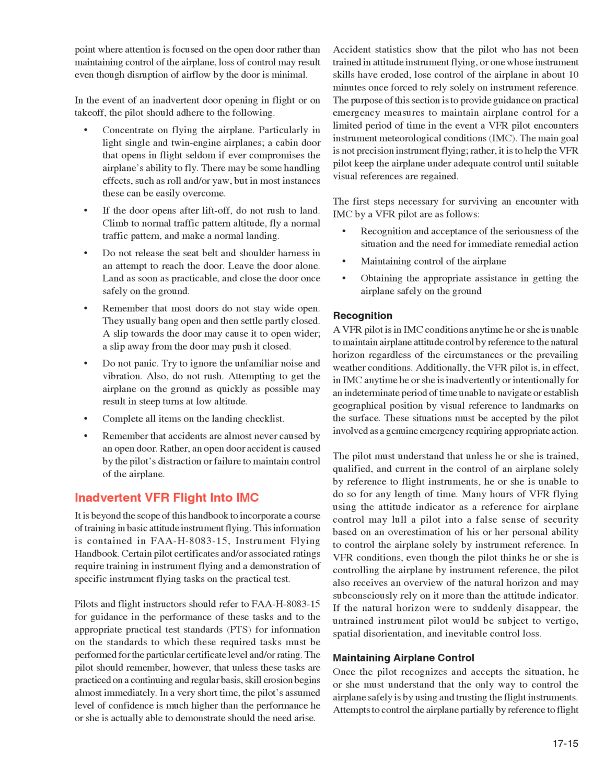The pilot should remember, however, that unless these tasks are practiced on a continuing and regular basis, skill erosion begins almost immediately. In a very short time, the pilot's assumed level of confidence is much higher than the performance he or she is actually able to demonstrate should the need arise. Accident statistics show that the pilot who has not been trained in attitude instrument flying, or one whose instrument skills have eroded, loses control of the airplane in about 10 minutes once forced to rely solely on instrument reference.